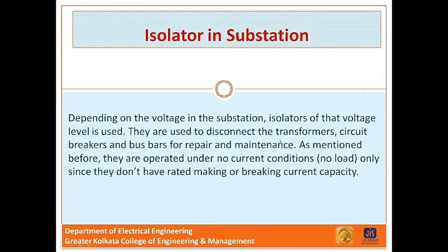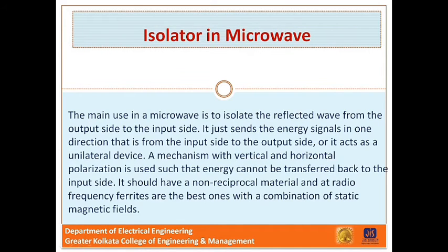They are used to disconnect the transformers, circuit breakers and busbar for repair and maintenance. As mentioned before, they are operated under no current condition, that is no load condition, only since they don't have rated making or breaking capacity.